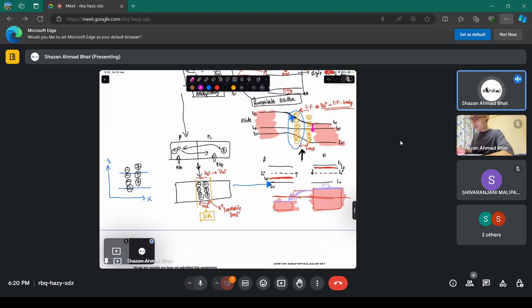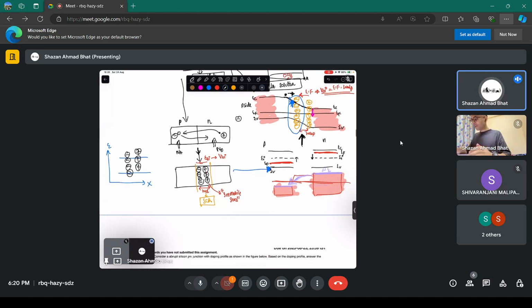This is because if you consider, let's say there was an electron, and it wants to come near that particular charge, it has to spend more energy in going to that region. So it has raised the potential energy at this region. Whenever you place the negative charge here, you raise the potential energy of that electron, because a negative electron and a negative ion are going to interact in a different way than a negative electron and a positive ion. So there is a change in the electrostatic potential energy of the electron, just from basic electrostatics, what you might have studied in class 10 plus 2 maybe. So that's how the band bending occurs, and that's what the band bending actually determines.